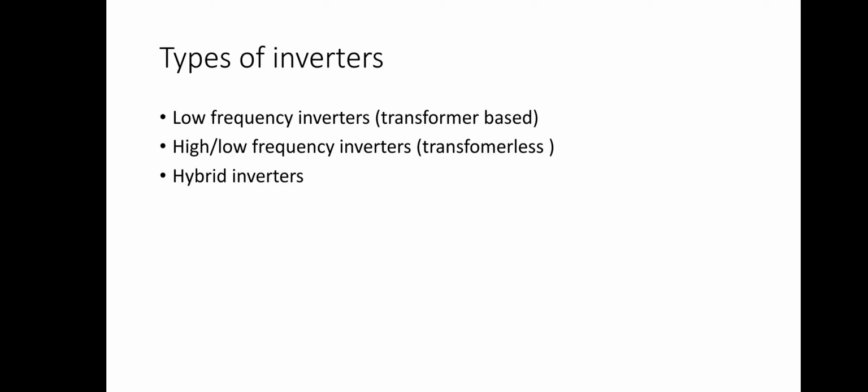So when your PV array is connected, when your inverter has an inbuilt charger inside, it is said to be hybrid, irrespective of whether the charge controller inside is PWM, pulse width modulation, or MPPT, maximum power point tracking. So that is what makes your inverter a hybrid inverter. The presence of your charge controller inbuilt inside the inverter makes it a hybrid inverter.